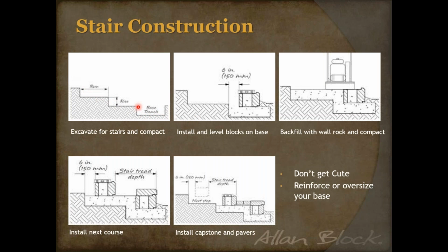That grid, I showed you how to use grid in curves, corners, and stuff like that. Ironically, I tend to recommend grid in stair applications because what does grid do? Grid holds soil together. And so even if you use that biaxial grid and just kind of lay it even at an angle here, that holds that soil together. So instead of acting as individual courses or individual steps, it acts like a staircase. It acts as one element, and it moves together that way. So that grid is great.